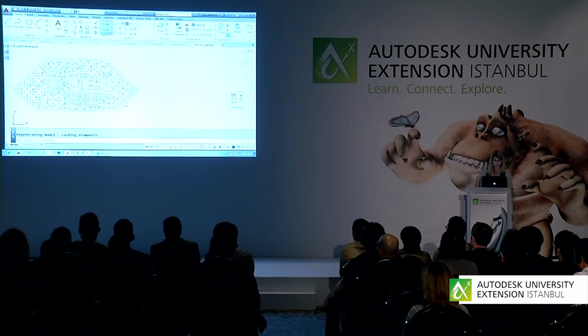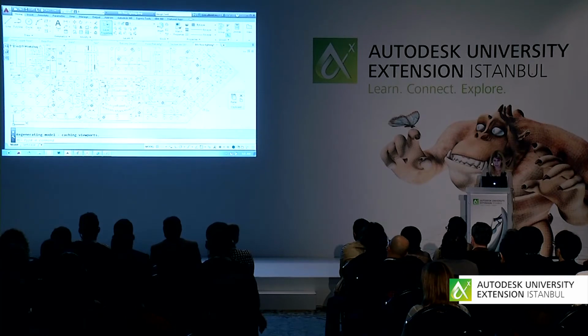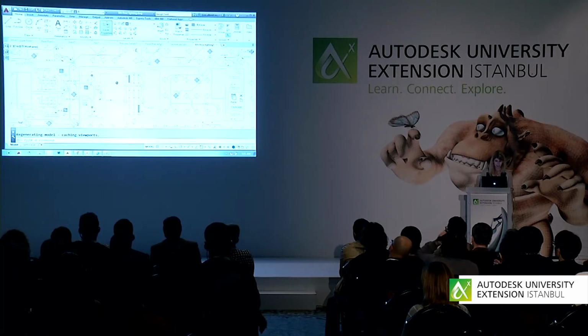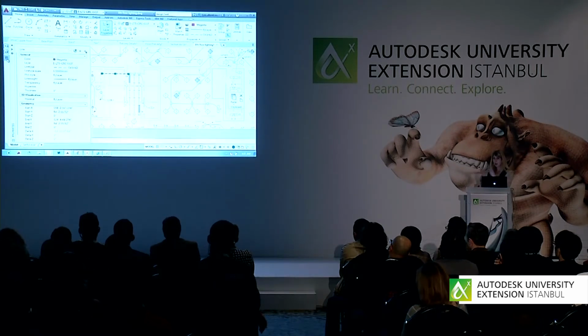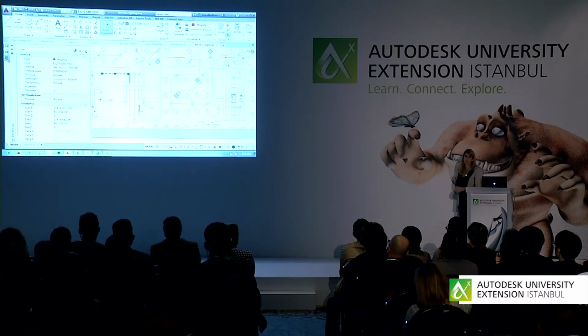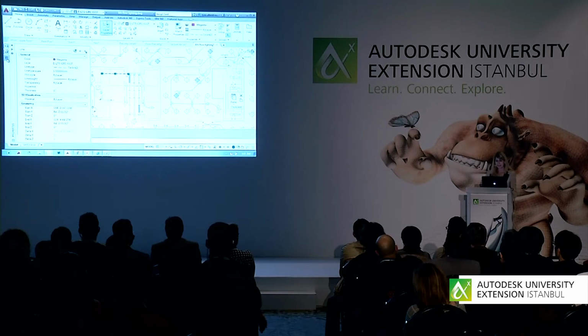However, if we take a look at the drawing, everything is definitely not gray. There are some objects that are cyan and some objects that are magenta. If I click on this object and go over to properties, you'll see that it has a color assigned to it. It's not by layer. In fact, it also has a line type assigned to it that's not by layer.